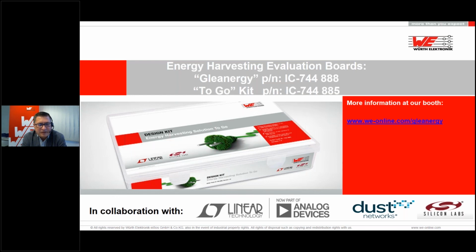Another question: harvesting from a Peltier element, is that possible? Minimum 30 degrees Celsius difference. Yeah. A Peltier element is also working like a thermoelectric generator, but I know that Peltier elements have been built a little bit differently. In a Peltier element, you give current to cool down one side and heat up the other. This is actually a kind of heat pump. A good TEG is actually not a good Peltier element, and a good Peltier element is not a good thermoelectric generator.